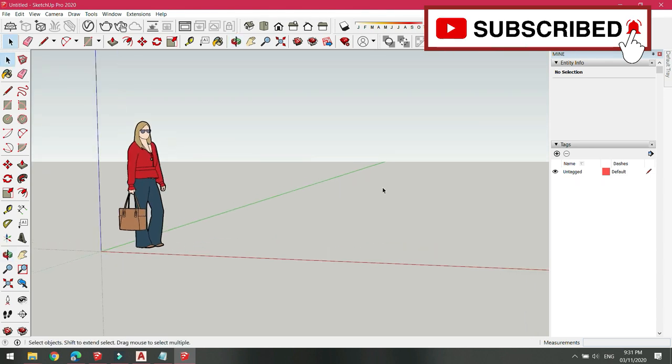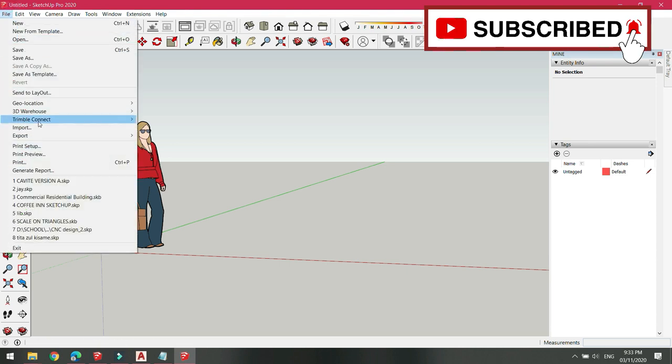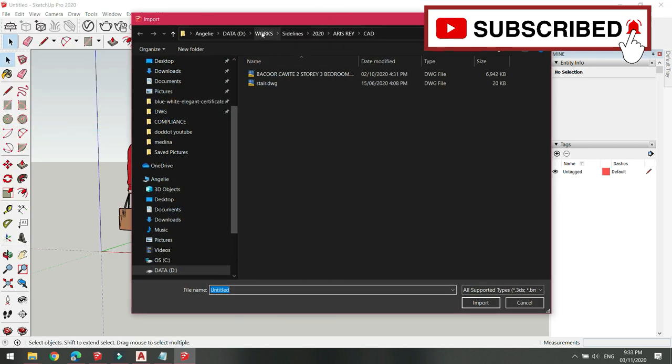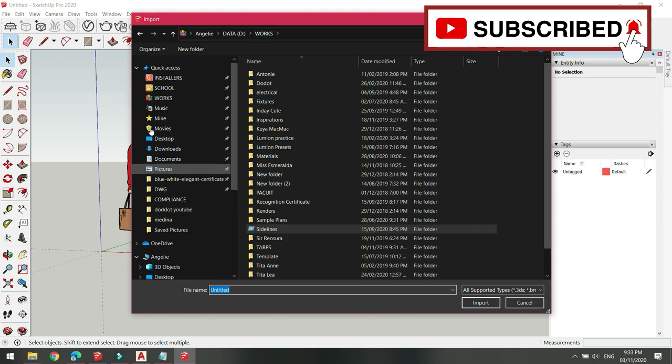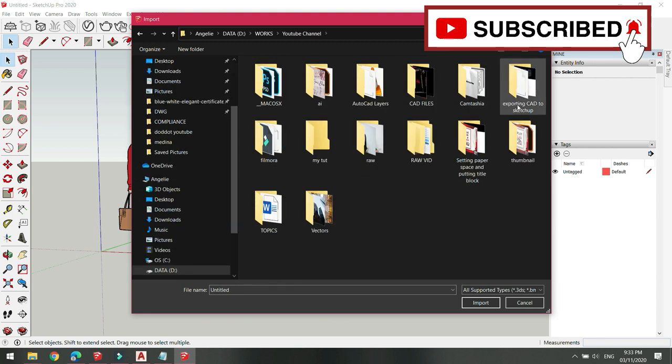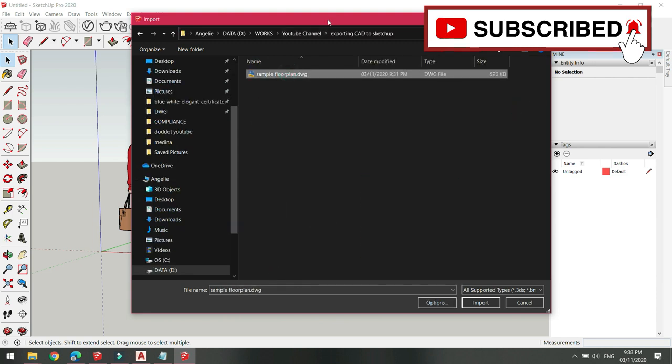So I'm going to import that AutoCAD file. So how do we do that? I'm going to go right here and click File. Then I'm going to click Import. Import means there's a file outside Sketchup and I'm going to bring that inside Sketchup. Then this will show up, and I'm going to find that particular file. Where did I save that floor plan? So here it is. I'm going to click that.